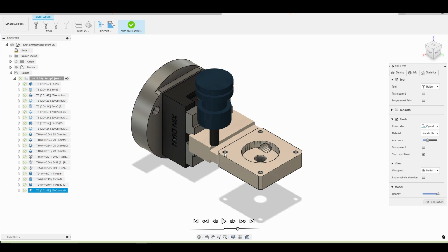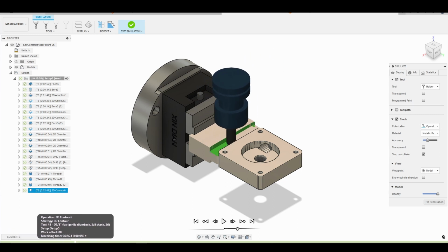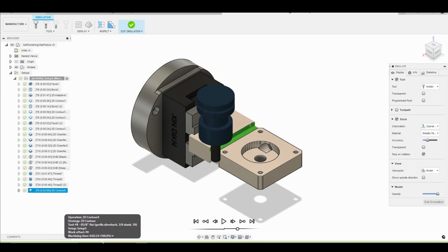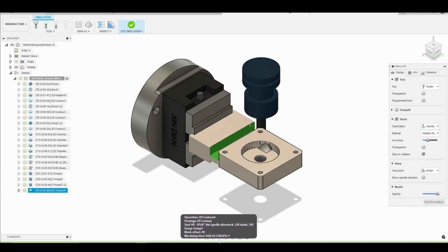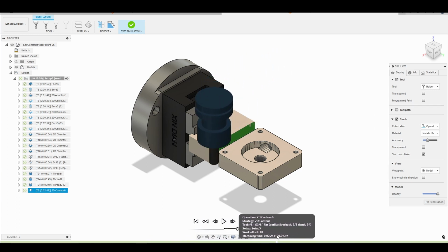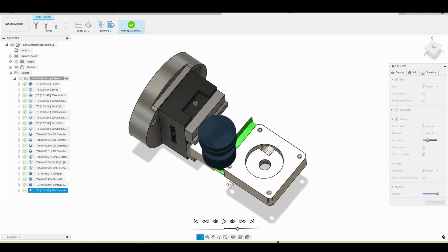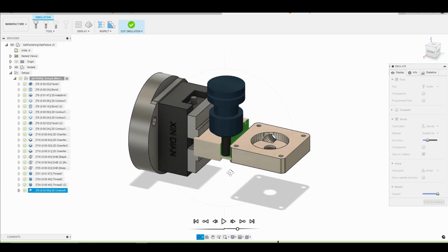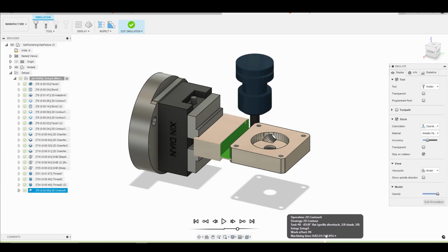What I ended up doing is just, again, putting my part in a vise and taking 5 thousandths off of the back. So we're cutting a little bit of air there. That's fine. Okay. And actually, let me orbit this so that we can get a better view of the tabs being created. It's hard to see in there.